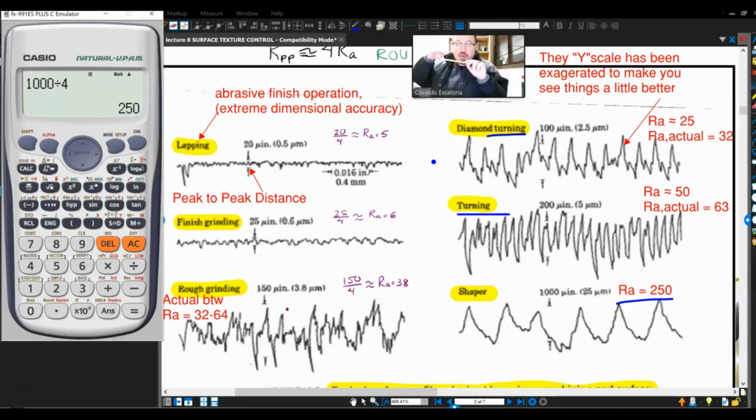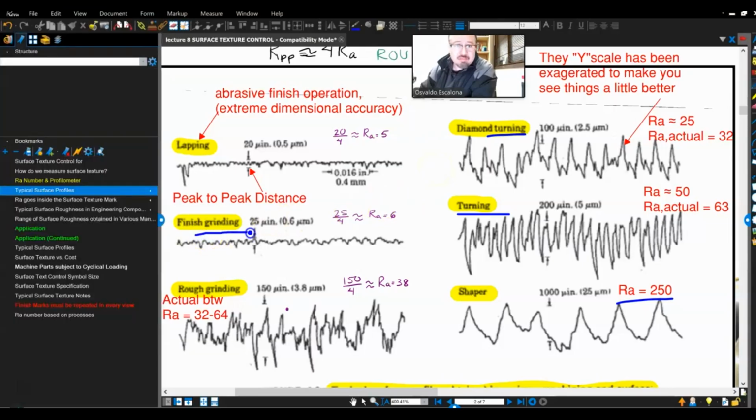You take more material in the roughing, and then as you're about to finish the part, you will have finishing turning, finishing moves, let's call it. So you take away less material, to make the surface finish better, right? You can also have grinding, right?